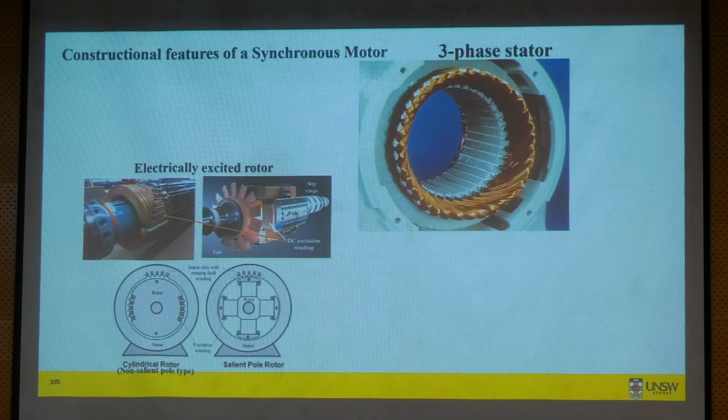We calculate it from power, right? We try to estimate the real power, and then by dividing it by speed, we calculate the torque. So to get the power equation, we need the electrical equivalent circuit of a machine, and then we use that circuit analysis to calculate the torque, right? So we'll try to recall that and see what is different if it is a PM machine.